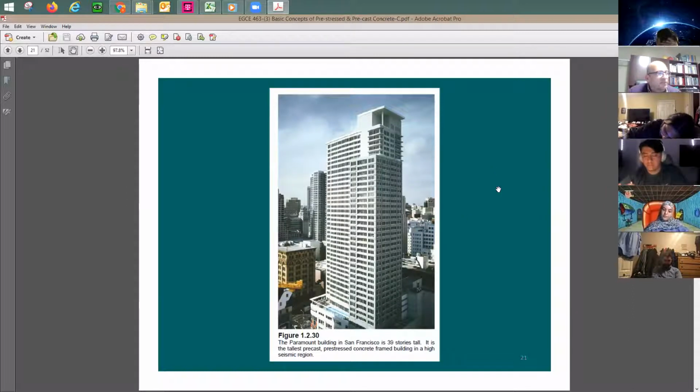This project here was designed between the years 1999 and 2001. And there are no reinforced concrete shear walls. It is a system called hybrid moment frame. The hybrid moment frames are pre-stressed moment frames. Code does not recognize this system. That was an invention at the time. That was something brand new. It was all new ideas. All the concrete slabs are all pre-stressed.